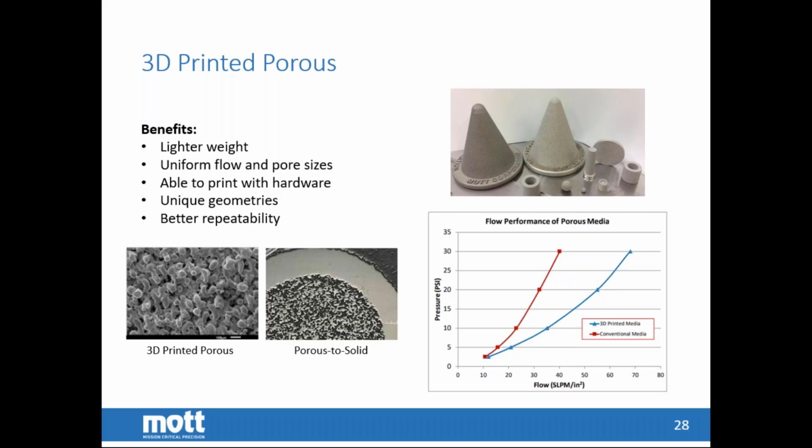In terms of the porous itself, you get a much more uniform density to give you more repeatability and better flow. Yeah, a lot of that comes from uniformity, where you don't have to press in an iso press or fill a die and then press and sinter, right? It's just laser bed, and that's where you eliminate some of those density gradients that you might see conventionally. That's exactly right.